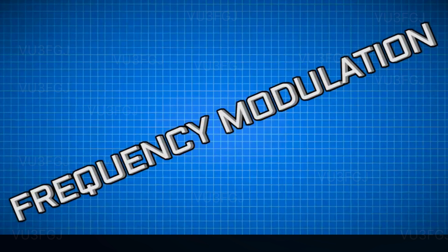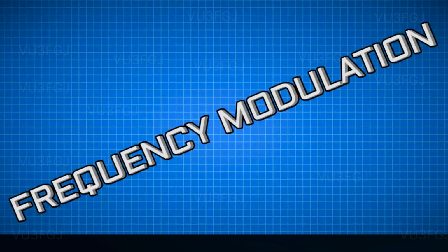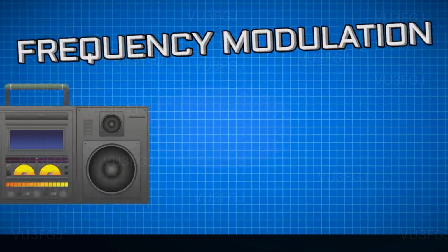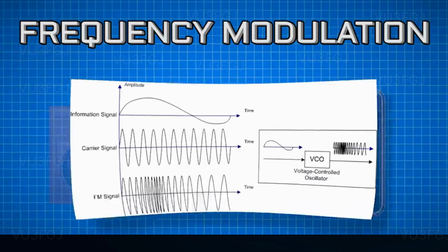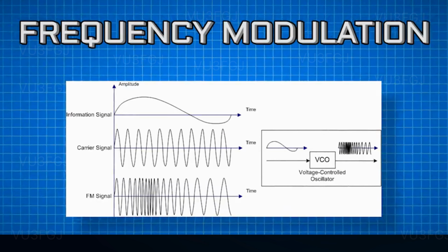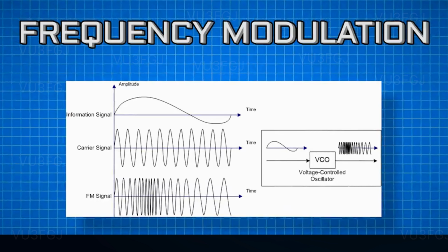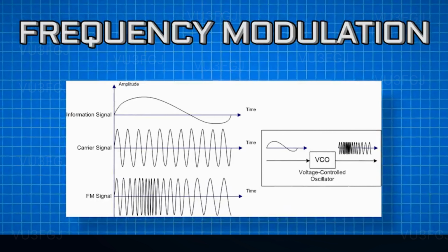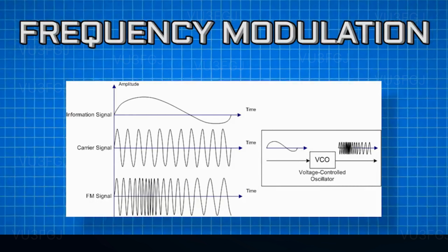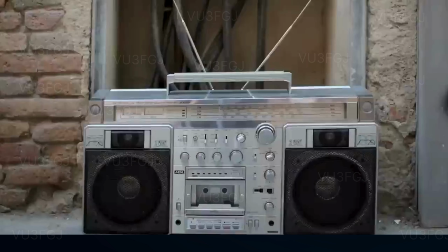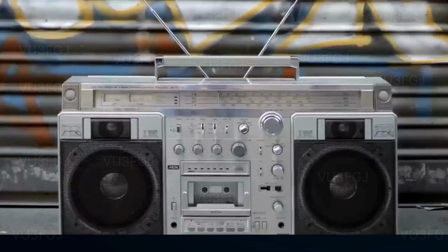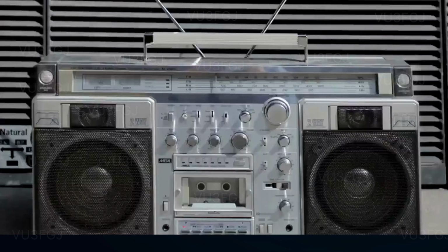Finally, frequency modulation, otherwise known as FM, is used for FM radio and tons of other wireless tech. In this encoding technique, the sine wave frequency changes slightly based on the signal. This means that the distance between the peaks of the waves is varied based on the data that's trying to be transmitted. Bringing all of these different techniques back into the real world, we can begin to understand them a